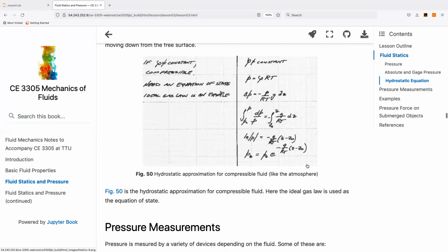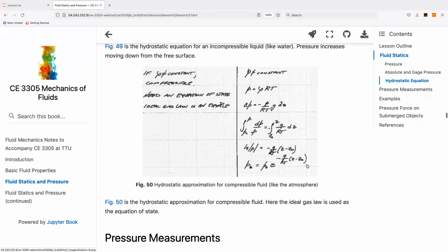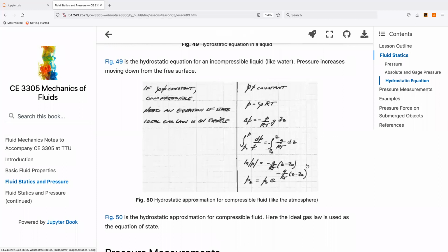So if you were boiling water, where would it take longer to boil? Well, we're at 3,000 feet. All that stuff's off. Houston to Denver. Okay, so if you're boiling water in Houston, you turn the fire on. What temperature is the water going to boil at in Houston? You're at sea level. 212 degrees, that's Fahrenheit. What would it be in Celsius? About 100. You go to Denver, so we're at 12.5 pounds per square inch. What's just changed there? The vapor pressure.